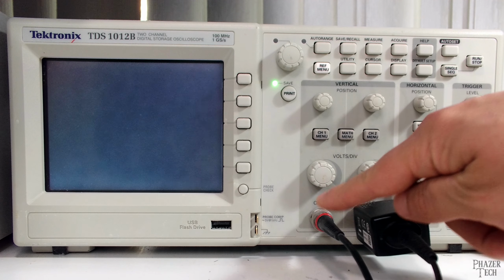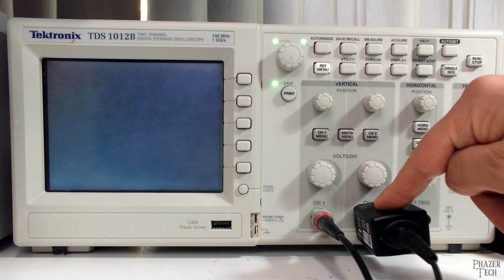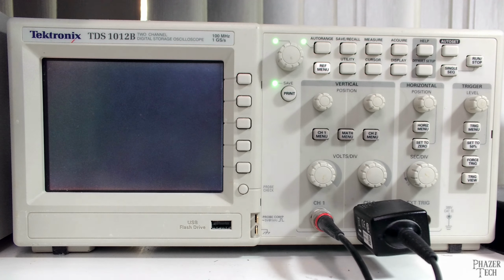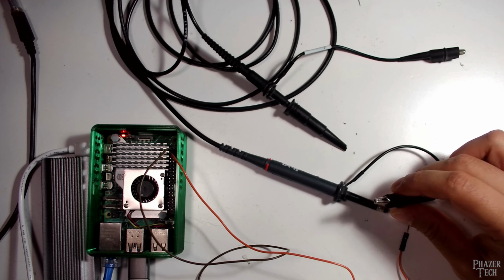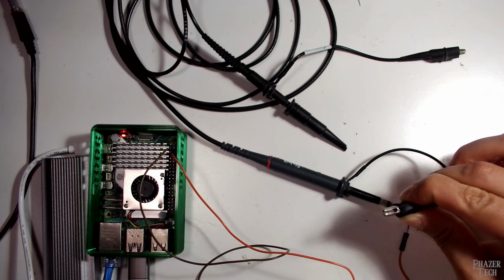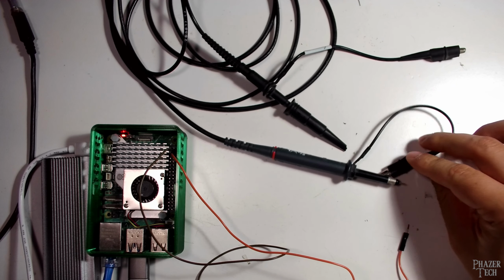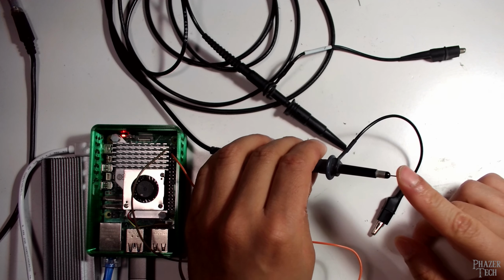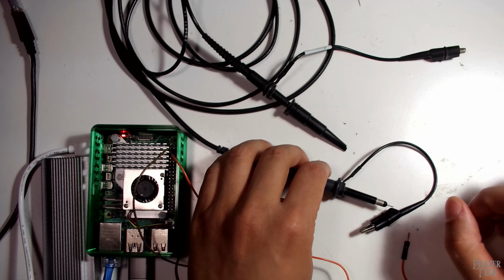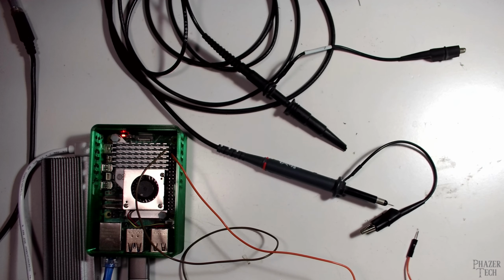probes. So as you can see, this is a 2-channel scope, and these probes are slightly different, but every probe will have 2 pins, a ground, and you can see this ground is this little alligator clip, and this particular probe has kind of a needle tip sticking out, and this probe is meant to make it easy for you to touch different parts or different traces of a circuit easily.